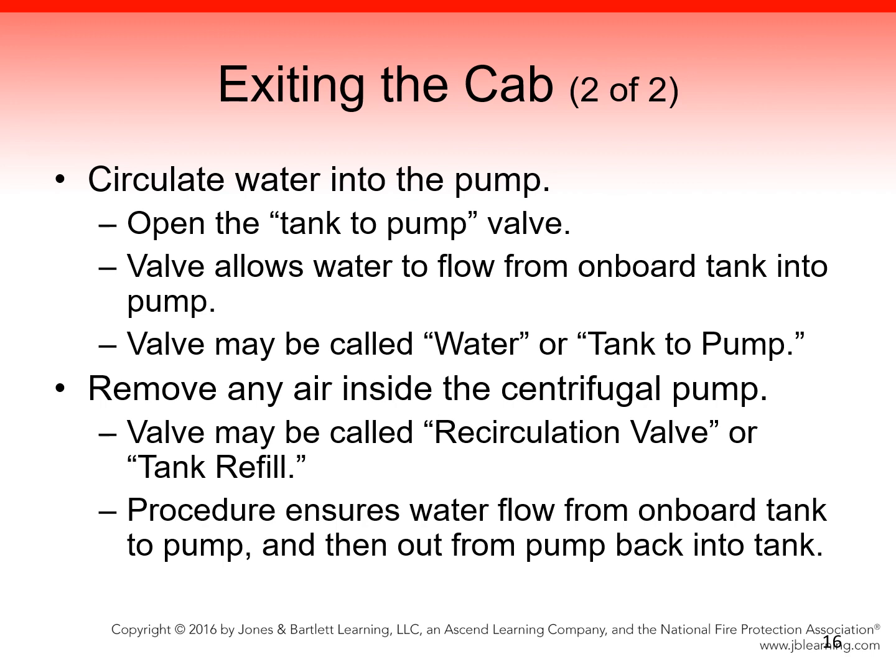Open the tank refill valve. This valve allows water to flow from the pump back into the onboard tank. It's basically a small discharge that directs water only back inside the onboard water tank. The label for this valve may carry any of several names such as recirculation valve or tank refill. Completing this procedure ensures that water flows from the onboard tank into the pump and then out from the pump back into the tank. This will help keep the pump from overheating. The steps for engaging the fire pump with an automatic transmission are summarized in Skill Drill 11-1.